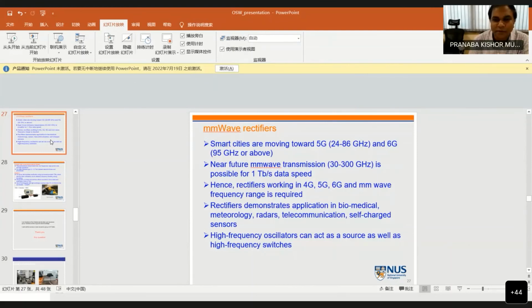Himanshu Fulara, you have a question? Yeah. Hi Raghav, it's a nice talk. I'm just wondering, does the frequency of the auto-oscillation decide this rectification sensitivity? I mean, does the rectification voltage you have observed depend on the frequency of the auto-oscillation? Yeah, of course. In the resonant case, it's a similar frequency to what we observe in the auto-oscillation. But once you have these very large amplitudes I have shown, you don't have auto-oscillations because your system cannot be excited at one frequency typically. Then you observe very broadband behavior, where you see many frequencies because the precession angle goes from in plane to out of plane, and it can cover many frequencies. But in the resonant spin diode, of course.